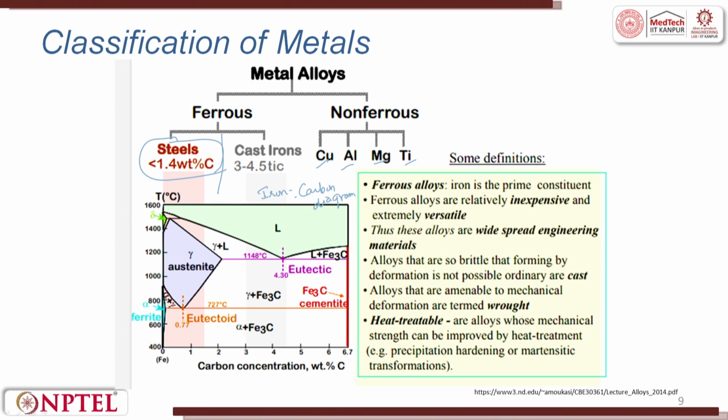So, in the x axis you will have carbon content. The maximum carbon content is 6 to 6.5. Generally, we do not go to that extreme end unless it is a specific requirement. What does that clearly say? Only this much weight percentage of carbon can be added to iron. In the y axis what we have is temperature. Temperature plays a very important role, because when the temperature goes high, the solid metal becomes liquid, and once it becomes liquid, the addition of carbon becomes easy.